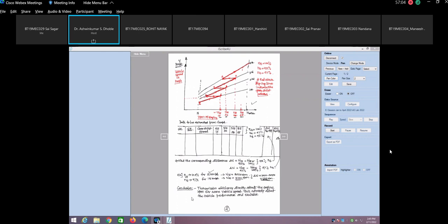As a result, there is sudden engagement and sudden disengagement. That means the clutch plate friction material is going to have certain problems, and that vehicle definitely will not give you better fuel economy and a better ride.